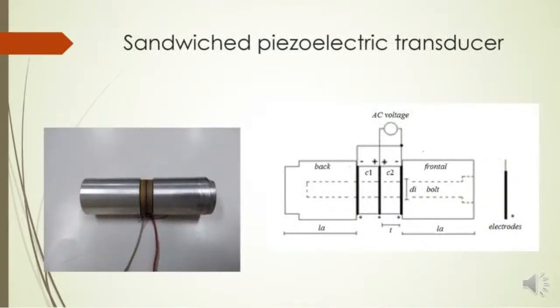In this figure, we see piezoelectric transducers and the respective schematic. Usually, the piezoelectric transducers employed in ultrasonic high-power applications are assembled with piezoelectric ceramics, metallic pieces, electrodes, and a central bolt. The central bolt tightens the transducer, applying the pre-stress. Typically, this pre-stress is around dozens of megapascal.